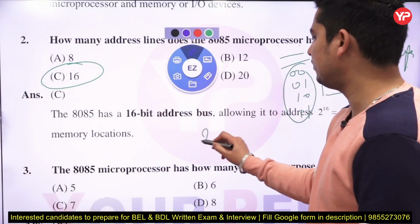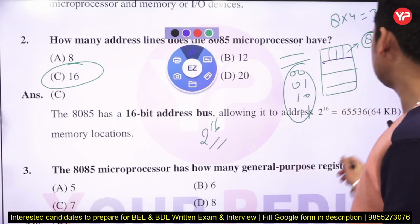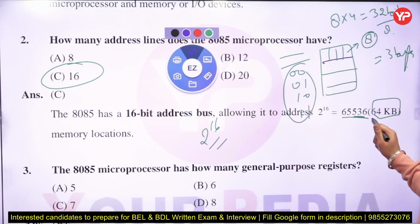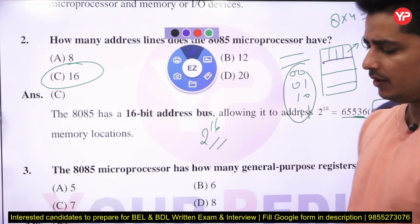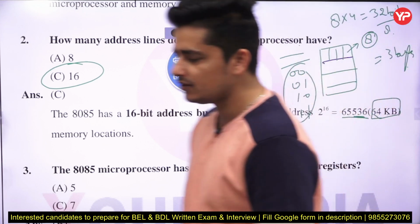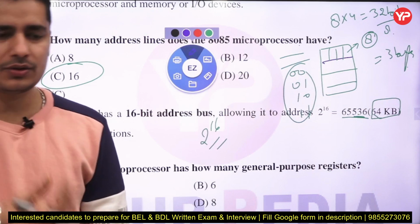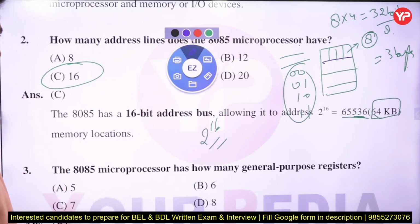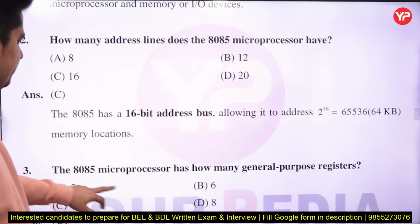That will be 2 raised to power 16, and if you convert this 2 raised to power 16, that will be 64 KB. So basically the limitation of this 8085 is that you can connect only a 64 KB memory with it, right? Not more than that. That is the main thing, right?